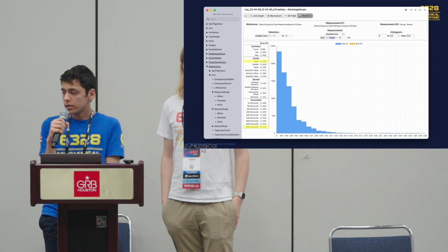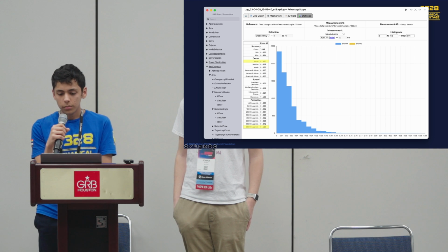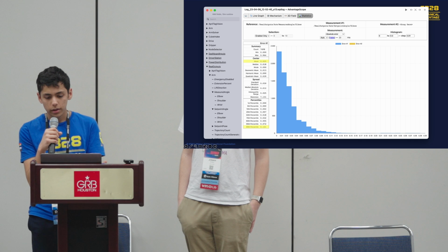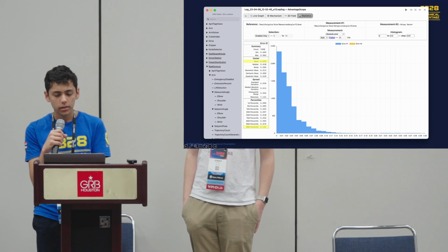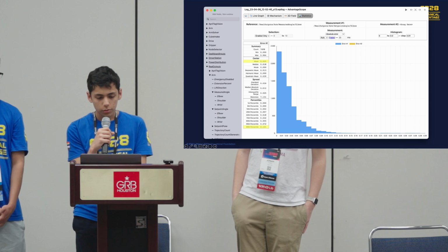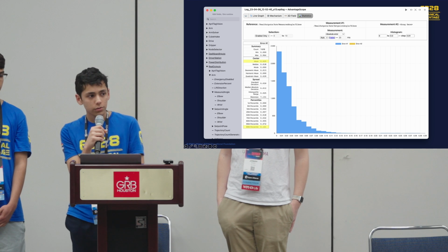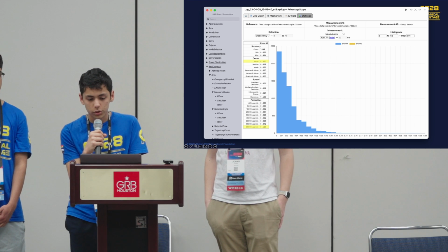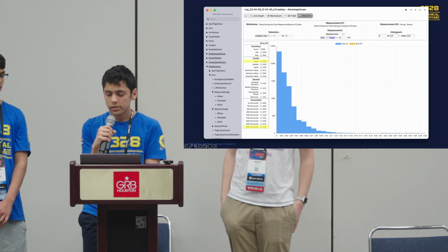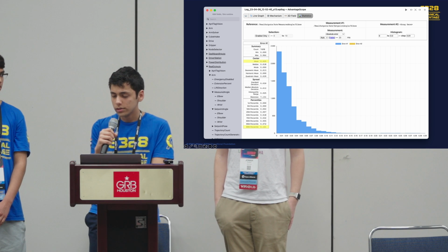Another useful view that we can use is the statistics view. AdvantageScope can automatically create a histogram like this, and it can automatically calculate multiple statistics, like the absolute error based on a measurement between the set point and the actual measured encoder value. Here we can see that AdvantageScope automatically created our average error for the elbow across a whole match. Our mean was 0.025 radians, or around 1.4 degrees, which is pretty good. You can also see other statistics such as the percentile. Here our 99th percentile is 0.121 radians, which means that 99% of our error is under 7 degrees, which is pretty good.